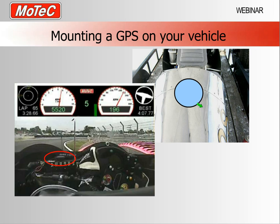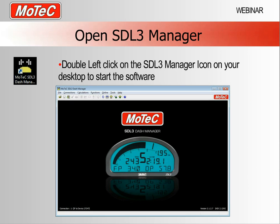So in these instances, where Peter's just placed that circle to completely cover what I'm trying to show to you, you'll see that they've placed the GPS on top of a metal surface. You'll have to take my word for that right now. And in the car on the left, which is actually a Le Mans prototype car, they've got a metal area on the top of the dashboard which has clear view of the sky in every direction. They're the types of things you would do to install a GPS in a car.